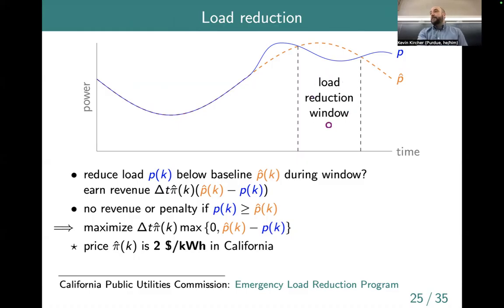So, for example, in California there's a ton of solar. When the sun begins to go down, all that solar drops off the grid, and then other resources have to ramp up really quickly to keep meeting demand during that time. That might be batteries, gas power plants, hydropower, things like that. But basically wholesale prices tend to go crazy during those periods because there aren't that many resources that can ramp up super quickly, okay?